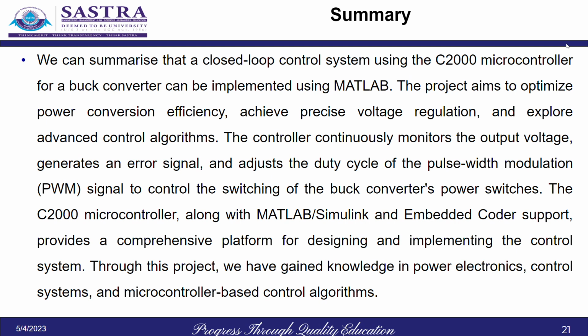The controller continuously monitors the output voltage and generates an error signal, adjusts the duty cycle, and provides a pulse width modulated signal, a duty cycle varied signal, to the switching device, and controls the buck converter power switches. The microcontroller, along with MATLAB and the embedded coder support provided by Texas Instruments, provides a comprehensive platform for designing and implementing the control system. Through this project, myself and my friends have gained some knowledge in power electronics, control systems, and microcontroller based algorithms.